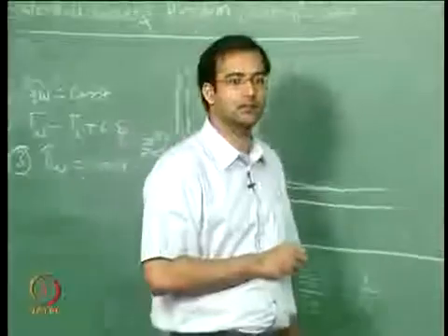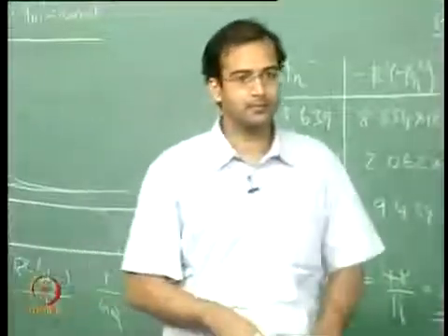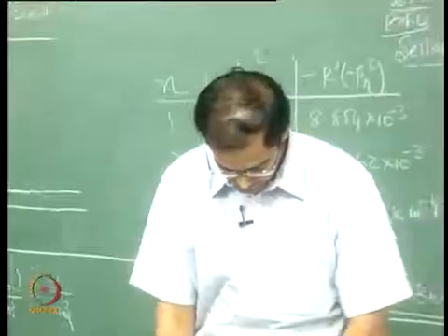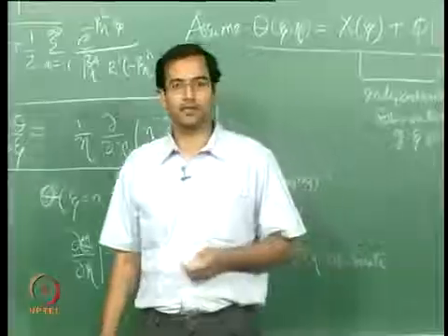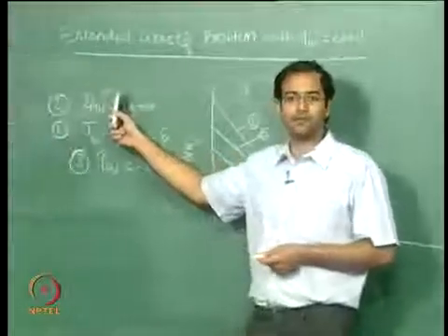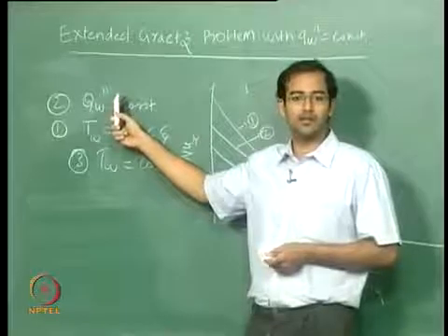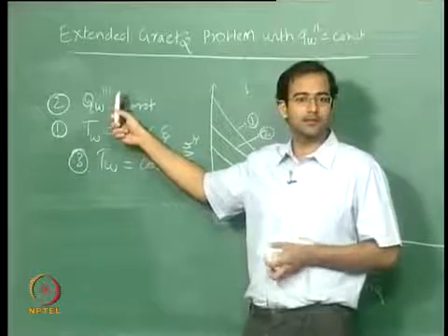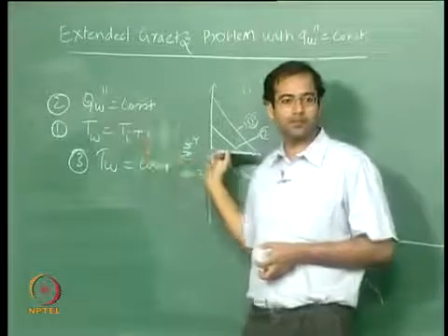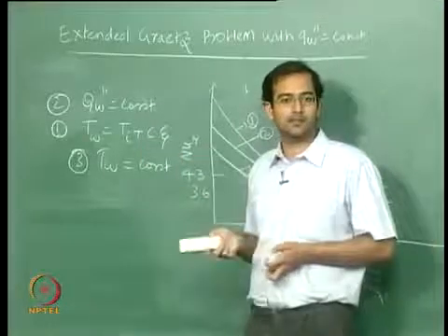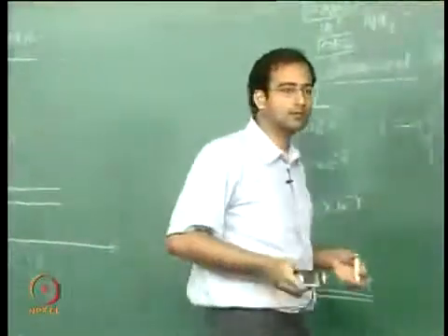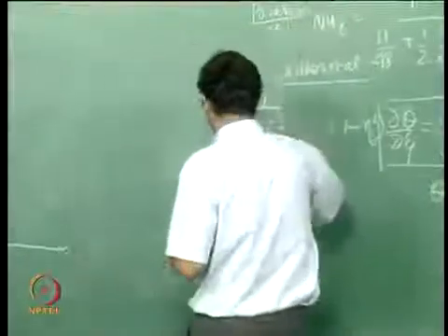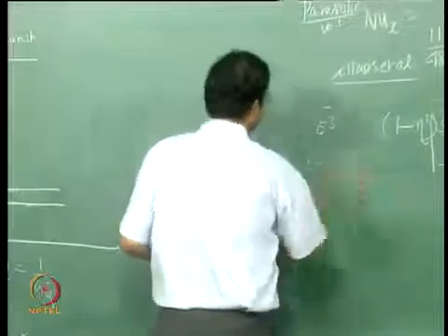Can you explain why the two cases give the same value? dT by dx is linearly varying at the wall, so that would be the same as T wall as linear. Correct, exactly. When you say Q wall is constant, in the fully developed case we have shown that the wall temperature varies linearly. So therefore it should approach the first case where your wall temperature is varying linearly throughout. So the two Nusselt numbers will have to be the same in the completely fully developed region.